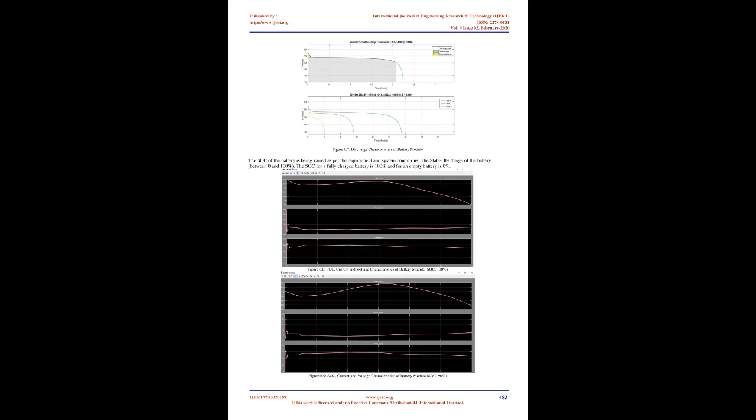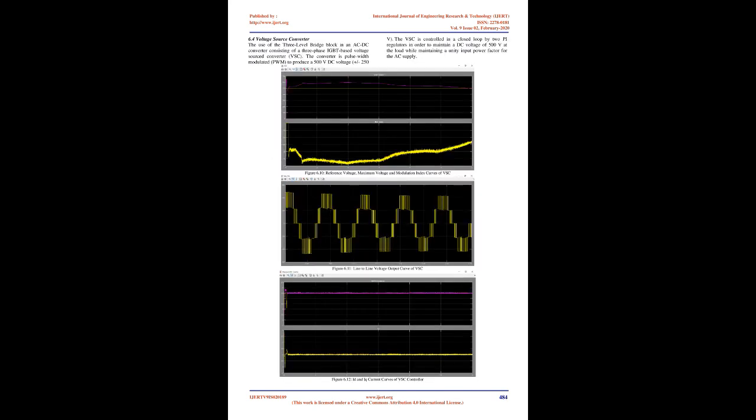Utility grid model: 25 kV distribution feeder plus 120 kV equivalent transmission system. For this detailed model, the electrical circuit is discretized at 10 microseconds sample time, whereas the sample time used for the control systems is 100 microseconds. Figure 5.6, Complete simulation diagram of grid-connected PV system.